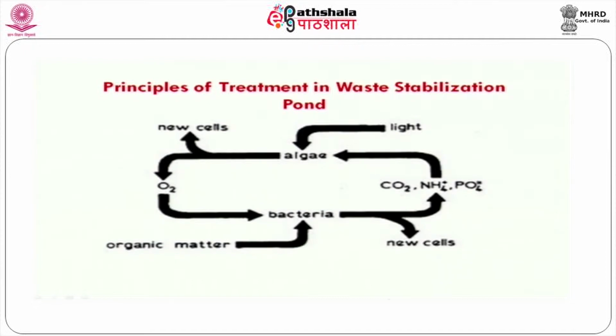During algal photosynthetic action, a huge quantity of oxygen will be liberated, that will be in dissolved state in the bulk fluid. Whatever oxygen is released during algal photosynthetic action will be utilized by aerobic bacteria as a terminal electron acceptor. The organic matter loaded into the reactor will serve as a substrate for aerobic bacteria. At the end of aerobic biodegradation activity, a lot of cells are released during the synthesis process. At the same time, the organic matter will be transformed into inorganic plant nutrients.